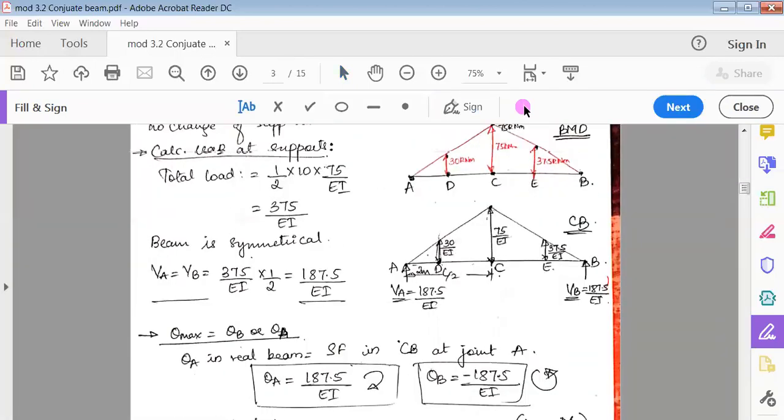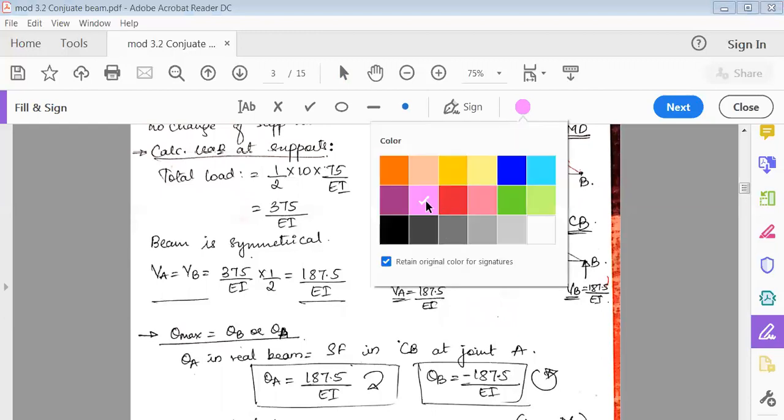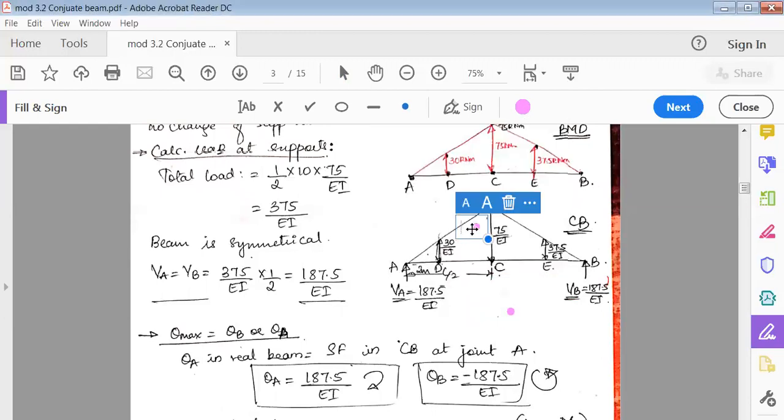So what I meant to say was, we are considering this complete triangle. You can see here, I'm taking AC, this portion. This complete triangle I'm using is acting downward. So the area of this triangle is half into base into height, into the CG distance.